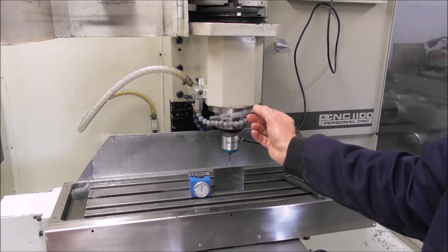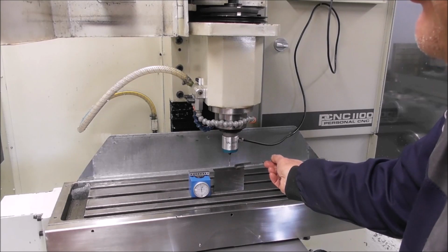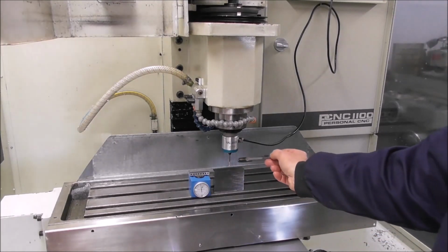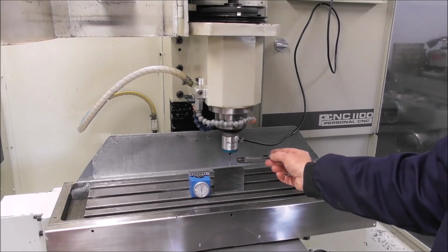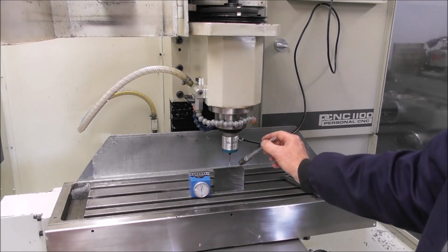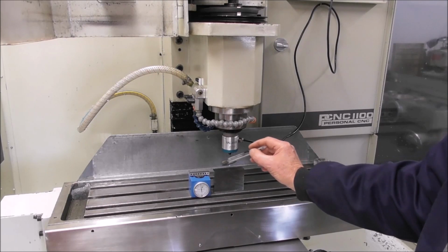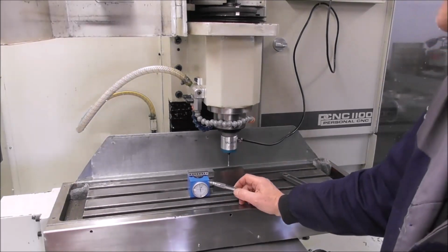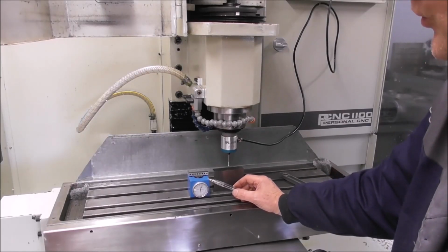So we've first set the tool offsets, and now we've just set the work offset, and that is on G54, the most normal work offset, but we could have also installed it on G55, 56, 57 and so on. So for G54, the software knows that that top surface is relative to the length of all the different tools that we've just measured.